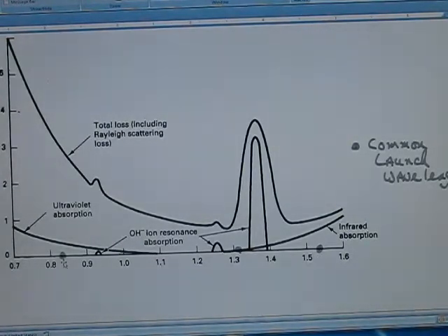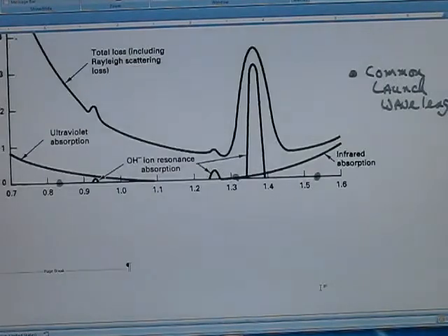So multi-mode is kind of local. The fiber optic cable is cheaper, and you can use light emitting diodes, and on these systems here you have to have lasers. So the wavelength is chosen such that we're going to try to pick up a minimum loss of the fiber optical cable that would maximize our distance.